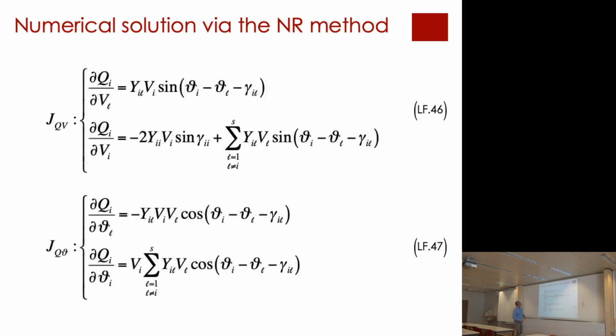And the same thing with respect to the reactive power injections, with respect to the amplitude of the voltage and the angle of the voltage. Again, these are given. Once you fix the load flow equalities, it's just a matter of computing the partial derivatives.